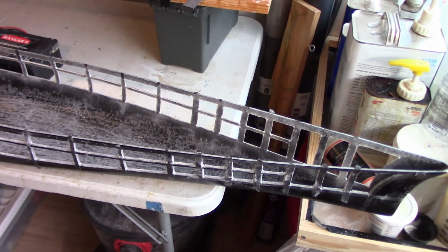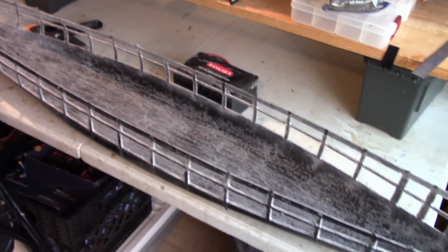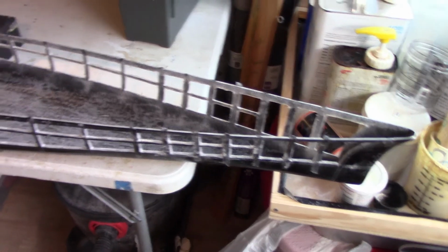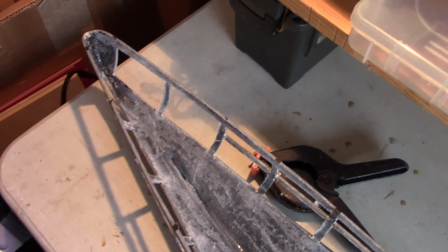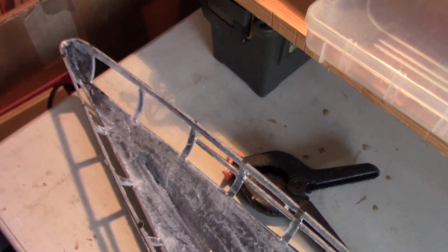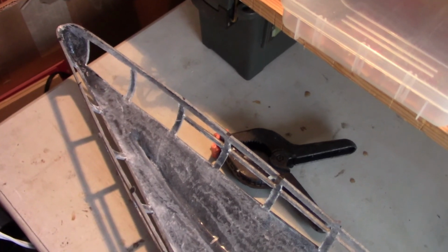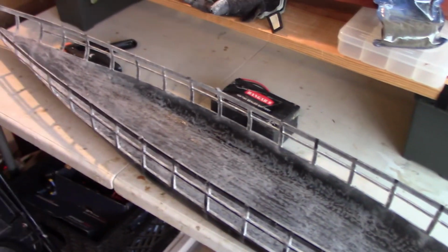I like cutting them out because it's easy to get access to the inside for some of those smaller areas where you can't really get the wheel deep enough. Also, if you look at the stern, how narrow the stern is, when you're cutting through there at the bottom, the wheel's going a decent way into the hull, so if my rudder mount was already installed, I'd have to be really cautious not to cut up the rudder mount as I'm putting the wheel through. And you could say the same thing along the deck edge, because you'd certainly risk cutting into the bottom of the deck. So I like to get this out of the way, and then from here, the next main steps are going to be figuring out what internal layout I want to do for the major spacing of the components, and then I'll move into installing the drivetrain.